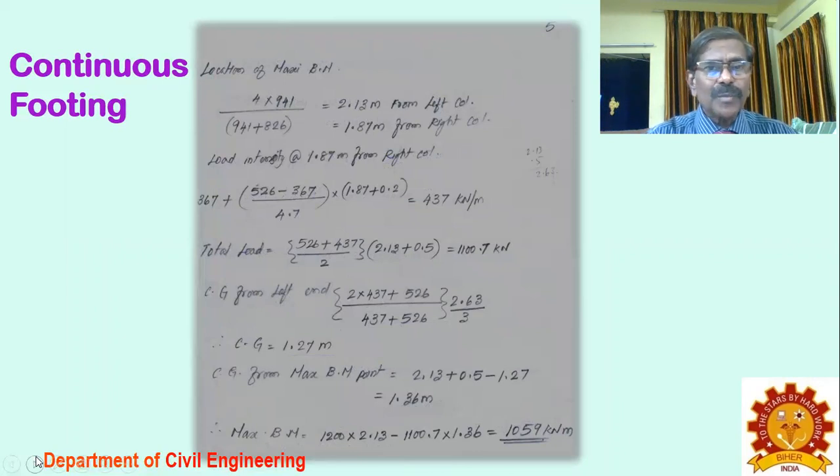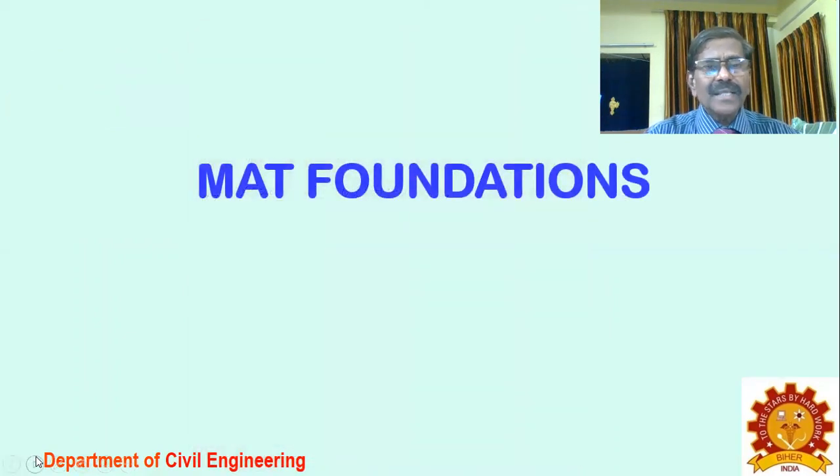Then the location of the bending moment you found out. Then for that bending moment, you design the RCC footing and find what steel area you may require. Then we'll go to the mat foundation or the raft foundation.